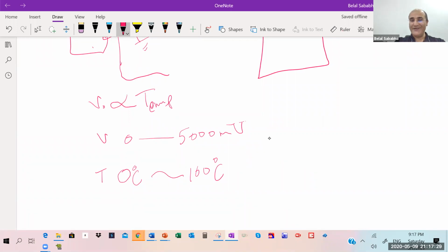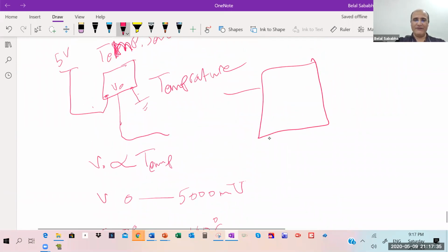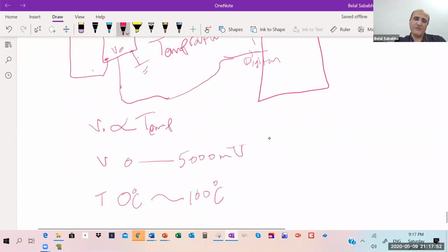Okay. So it's not going to work to say, okay, if we bring a sensor here and put it on a digital input pin, if I connect this voltage here, I'm going to be able to recognize the temperature as 1 or 0, right? Because the voltage level is going to be converted, depending on the thresholds, to 0 or 1, right?